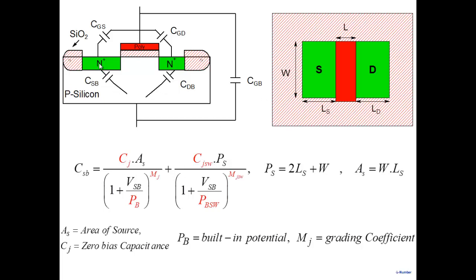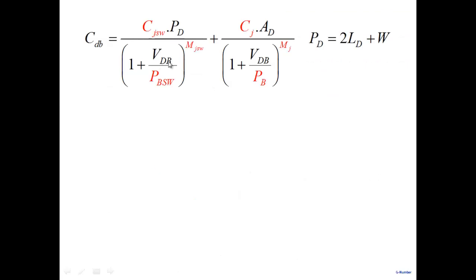And whatever I've said about source to body applies to drain to body also. It is the same thing here, except that the drain to body voltage will be different. Otherwise, the expressions are exactly the same.